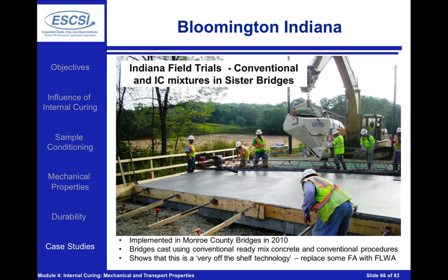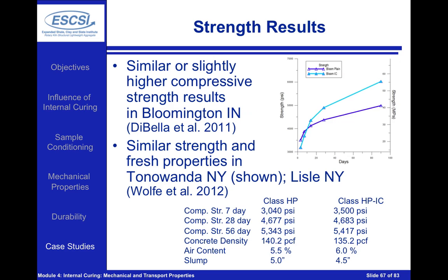This was done on the first project due to potential pumping concerns. I will mention that there are no pumping concerns we've had on projects since then, and in fact we pump the concrete and don't have any additional problems with pumping the internally cured concrete because most of those, we have a high degree of saturation in the pores, so we really are seeing that the internal curing is not really affecting the pumpability of the concrete at all, and we place it with pumps now on a consistent basis. Here we can see some of the results from those Bloomington projects.